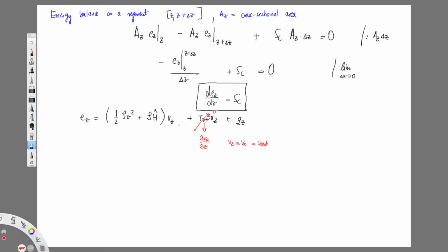We will need the concept of effective K for this packing of spheres. It's not the sphere material itself. I have spheres and fluid moving through spheres, and I'm averaging things. So the moment I'm averaging, I need the concept of effective thermal conductivity.